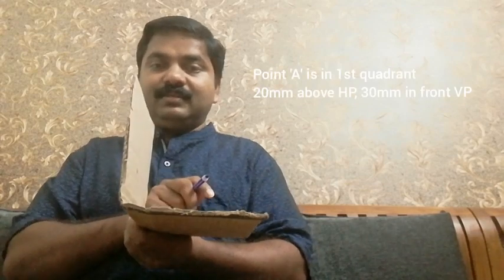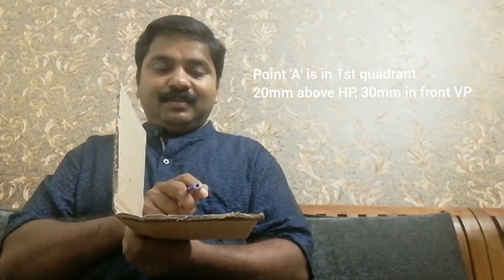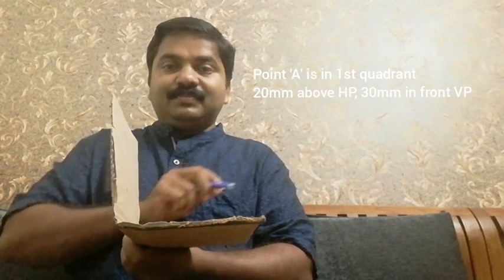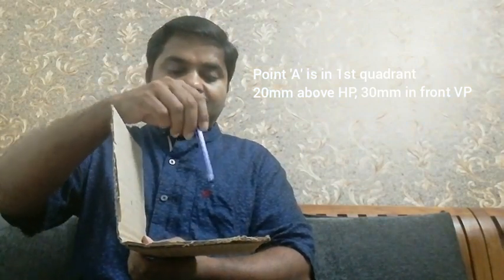So this is the first quadrant, second quadrant, then third quadrant and fourth quadrant. Now suppose a point is here, 20 mm above HP and 30 mm in front of VP. The point name is capital A. The person is looking from this direction, so the front view will be obtained here, and the top view will be obtained here.